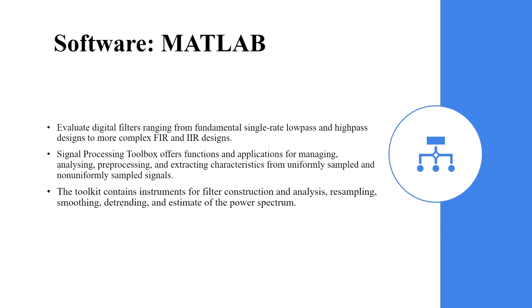For the software, we are using MATLAB. MATLAB is used to evaluate digital filters ranging from fundamental single low pass and high pass designs to more complex FIR and IIR designs. The signal processing toolbox offers functions and applications for managing, analyzing, pre-processing, and assessing characteristics from uniformly sampled and non-uniformly sampled signals. Next, the toolbox contains instruments for filter construction and analysis, resampling, smoothing, detrending, and estimating the power spectrum.